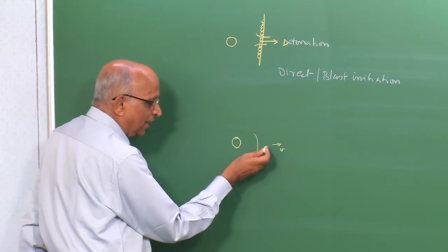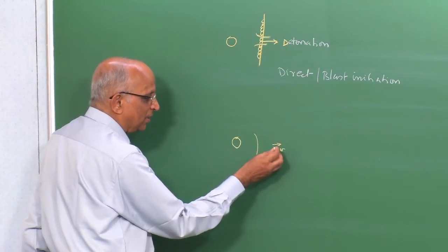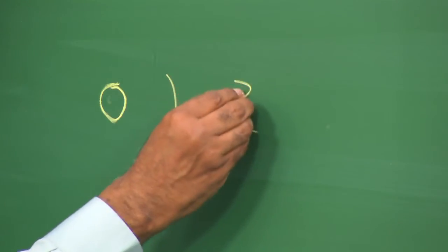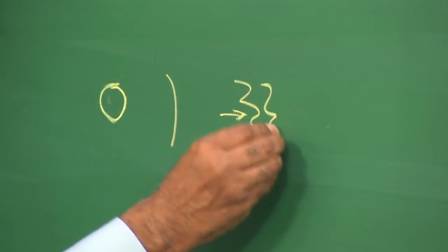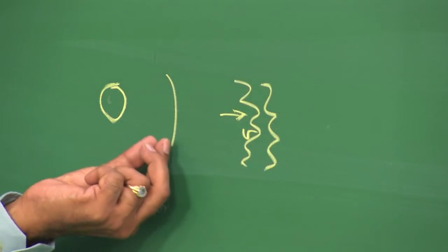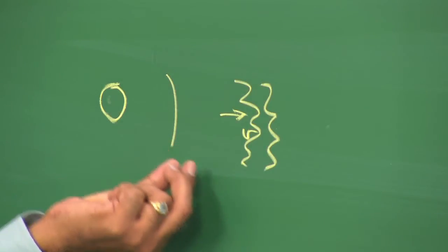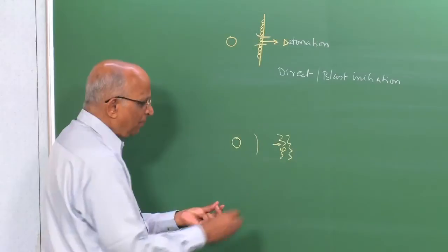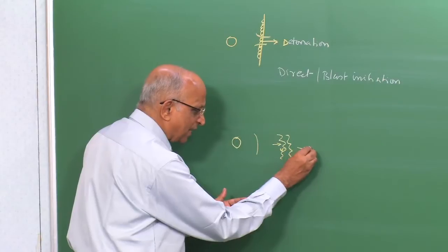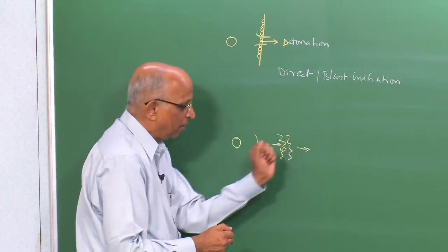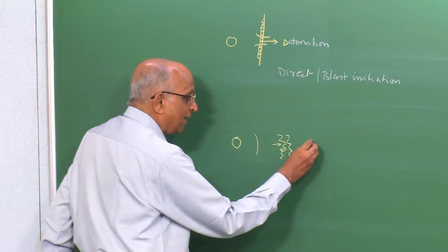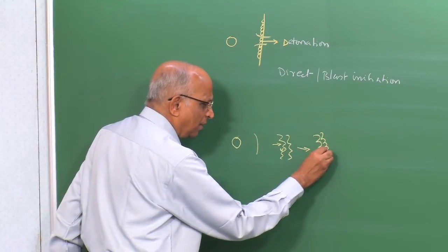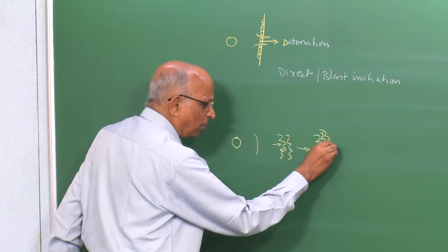Not only that, when the gas velocity is increased, maybe the intensity of turbulence increases, the length scale changes, and therefore you form something like a corrugated flame. Compared to a few centimeters per second or a few meters per second, this velocity is much higher because it is a turbulent flame, and ultimately this turbulent flame again drives the gases ahead of it, just like an accelerating piston pushing the gases. Therefore, I have a highly turbulent, highly wrinkled type of flame which is formed.